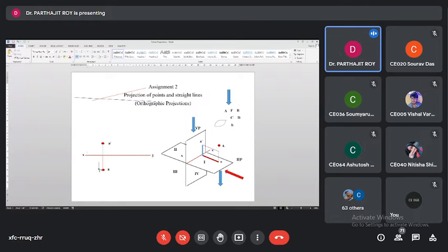And this blue color line I am showing now, this one, this is called extension line. Do not put your extension line in touch with the projection points. Let's have a gap of 1 millimeter. And length of the extension line maximum you can take it 8 millimeter.